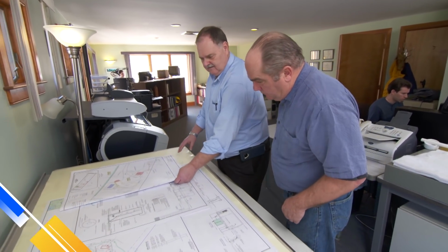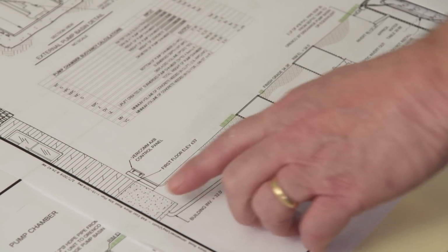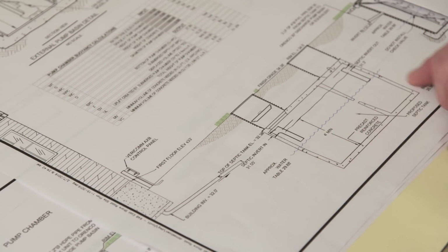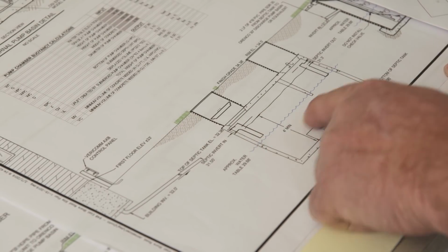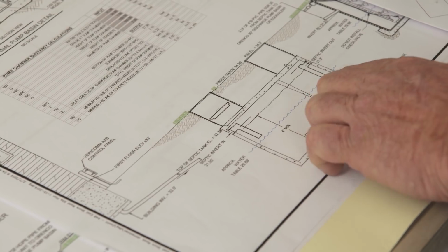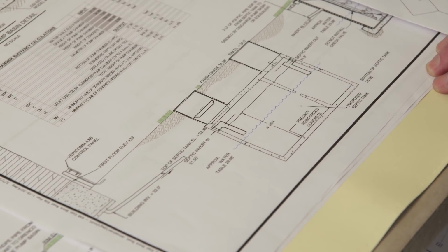We have a conventional system here. We have the house here. The flow from the house is going into a conventional septic tank. The solids are settling in the tank. This is the tank I've always understood. Yep. Solids and liquids come here, settle right to here. Bacteria breaks it down. The liquid, the effluent, leaves this way and goes out to the leaching field. Correct. So is that what we're going to use here?